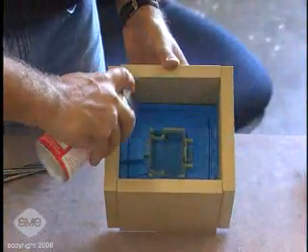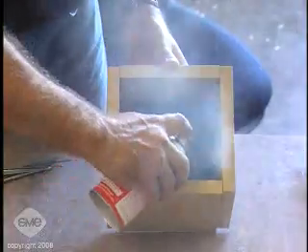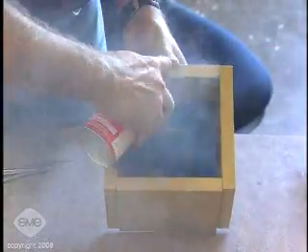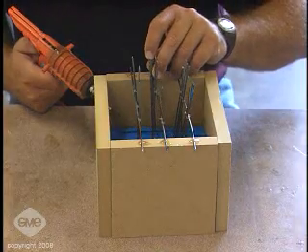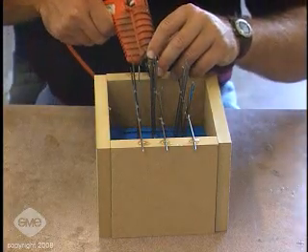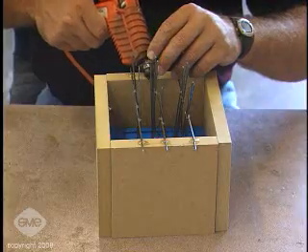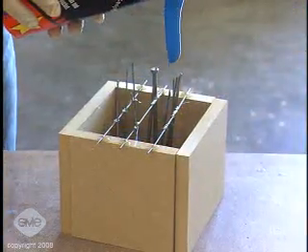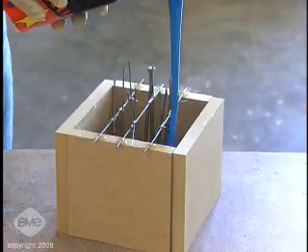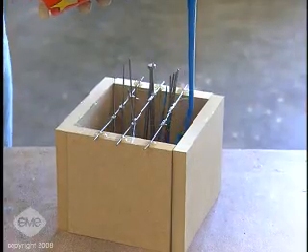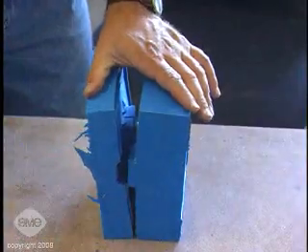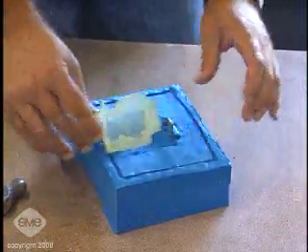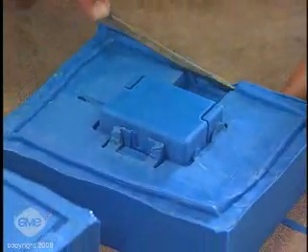This preparation can include a release agent coating to ensure separation of the mold halves, and the inclusion of a gate for injection, and venting to allow air in the mold to escape during the injection. Once prepared, the second mold half is poured and allowed to cure. Once entirely cured, the mold halves are separated along the parting line. The pattern is removed and the mold is prepared for use.